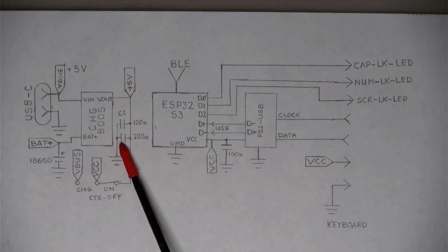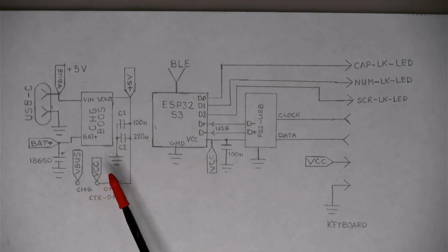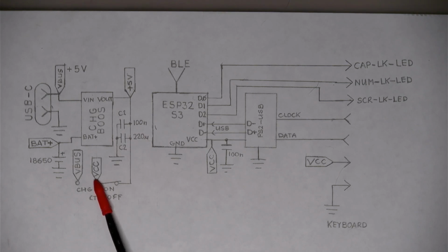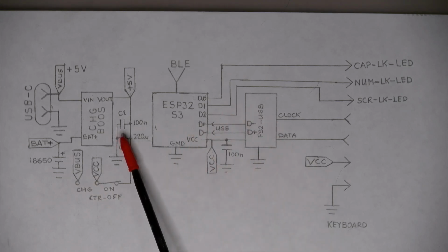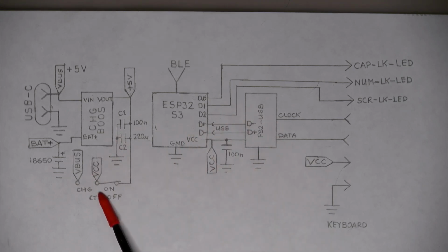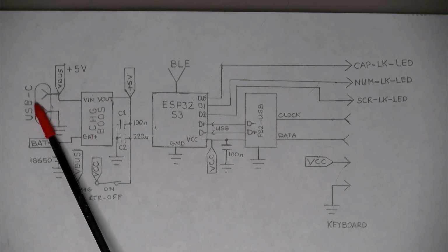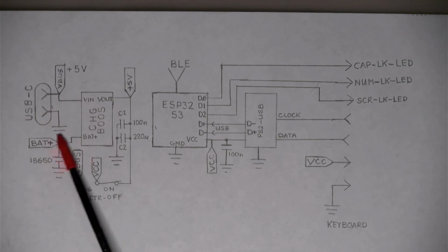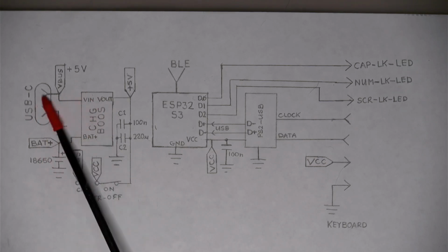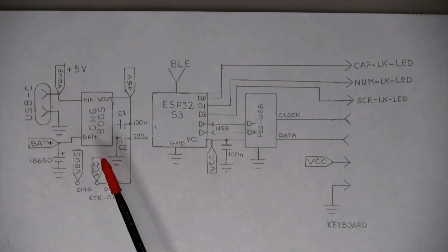So therefore, when the switch is off, neither one of those poles is connected, so there is no VCC, which is of course going to these different places here, which means that if it is off and you've got the USB-C cable plugged in, it will still be able to charge. It's got V in and it'll charge the battery, so that's simply charging only.